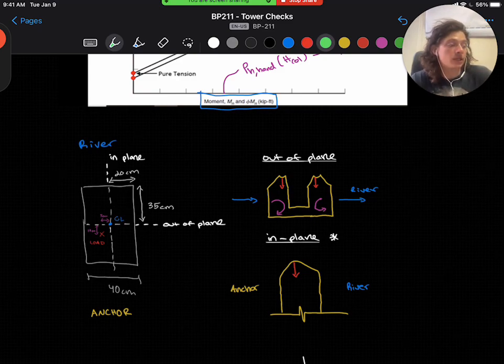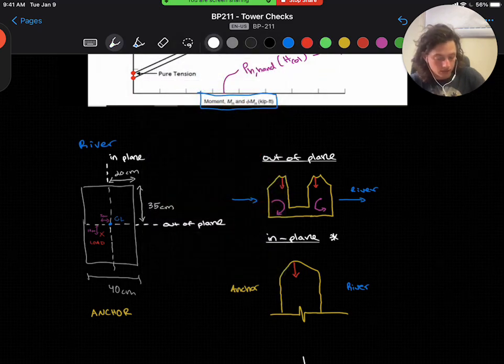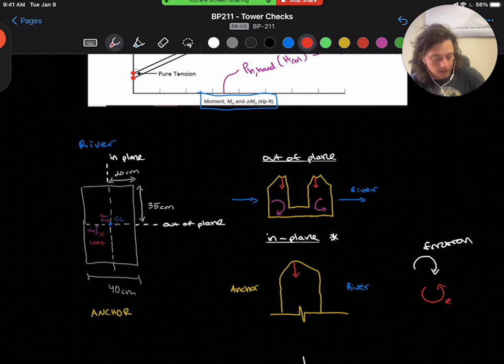Now, a plan view here shows those two eccentric moments, and remember that this should be subtracting from the net moment towards the river, right? Because our in-plane moment is set back away from the center of mass, so because of that offset, we are going to get two moments. One, we'll say here, right, is due to friction, and then due to what I've drawn in red, we'll actually have an opposite moment from the eccentric load.